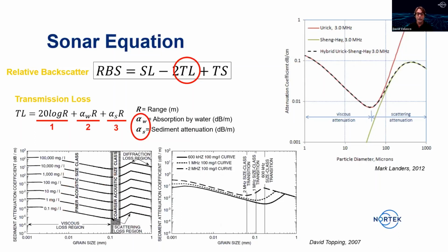That is basically a decrease in attenuation as a function of increasing grain size for fine particles, but then increasing attenuation after particles increase in size from clays to silts. On the right bottom graph here, from this reference, it shows how different frequencies respond differently to grain size, especially around the clay-silt transition zone, which is really important for many applications.